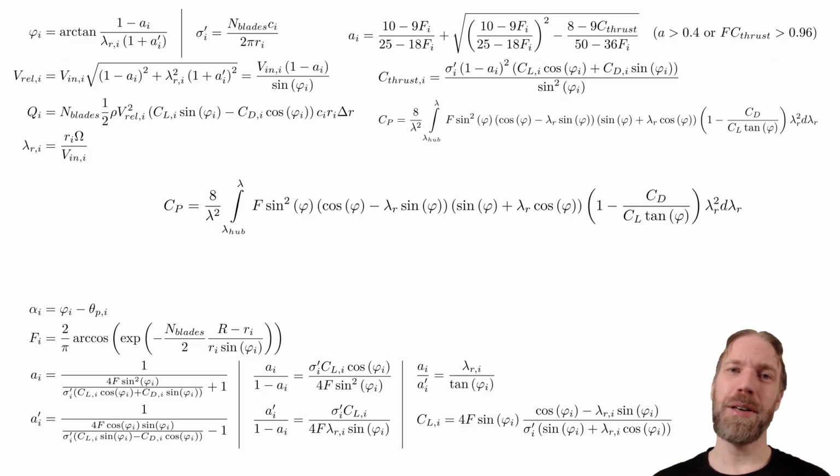So why is this equation still useful? It's an equation for the power coefficient that basically only depends on one variable. Since we can choose any angle of attack by changing the section pitch angle, we can consider the lift to drag ratio of the airfoil as a constant that we maximize. Therefore, our only variable is the angle of relative wind. So if we want to find the optimal performance, we only need to find the optimal angle of relative wind.